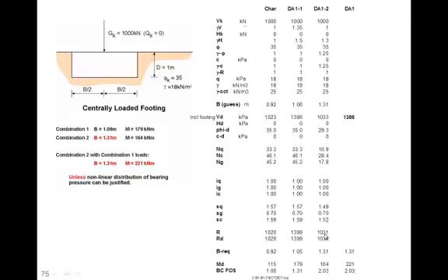which means that the design resistance of the footing, even though we've assumed 1.31 width, the design resistance is only 1031. Well, good enough for 1033, and therefore we can live with a 1.31 wide footing with our bending moment of 164 kilonewton meters. But as I said earlier, we have to check the 1.31 wide footing with the load factored up, and now including the weight of the footing itself, it comes to 1386, and we get our bigger bending moment. That's how the calculation would run.